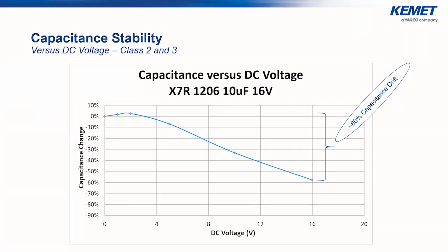So if that capacitance is decreasing over time, I would expect the resonant point to move out, to move to the right a little bit. Your capacitance is decreasing. So we can't really get around the physics with that. It is what it is.